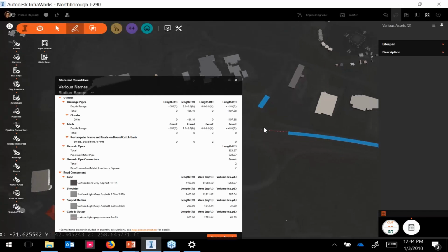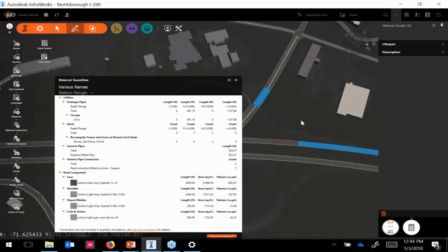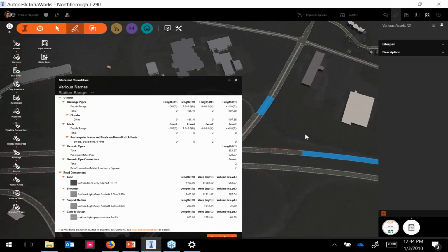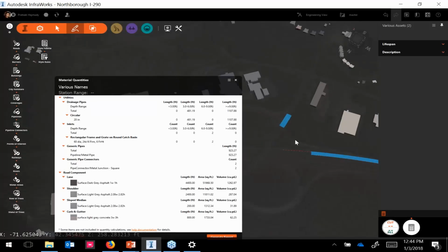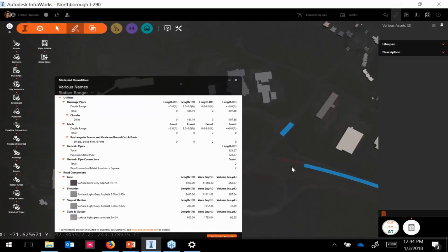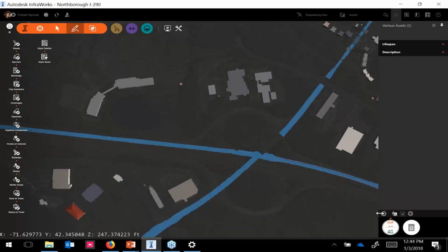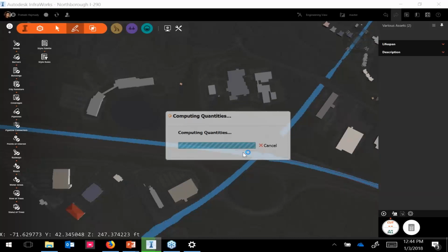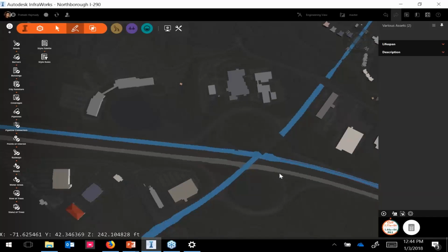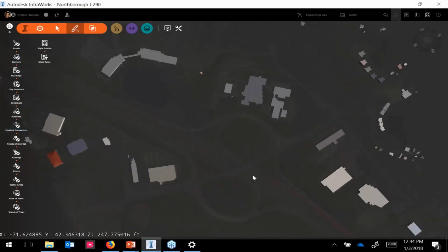In this case, obviously they don't have an intersection. But if you did have intersections, for that region we would not be able to calculate the material quantities. But we do provide that for other scenarios where you could start seeing this selection-based view. So you could set custom ranges for different sets of roads and use that aggregation to compute the material quantities. The same could be done for cut and fill volumes. And cut and fill volumes calculates it for the intersection regions as well.